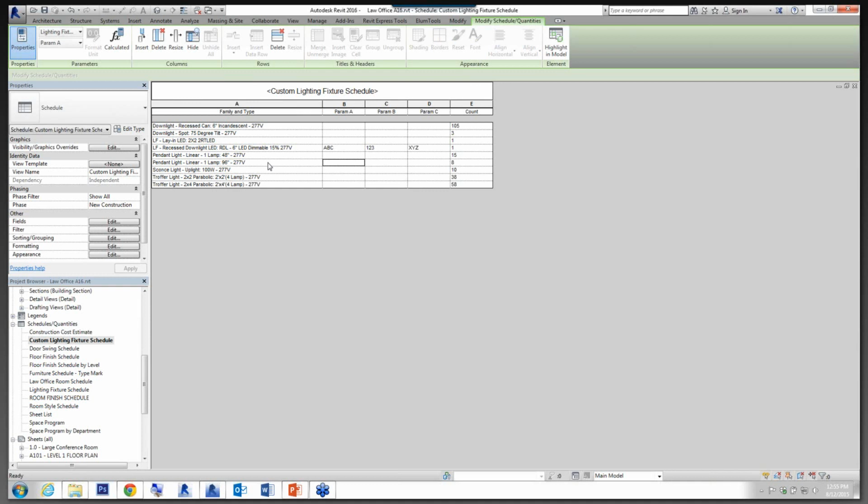And in that case, when you select one thing, like in all your air handling unit parameters are in the mechanical equipment category. And so when you select a pump, all your air handling properties show up.